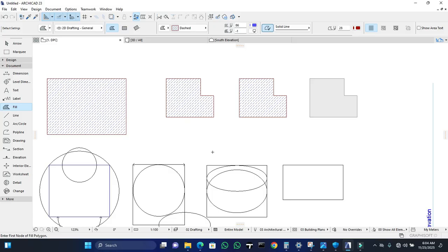So that's the easy way to set some things. Maybe if you drew a particular type of hatch throughout a document and you for some reason change different shapes, so you can just pick up the parameter from the first one you've edited and inject to the rest. Easy peasy, you are good to go.